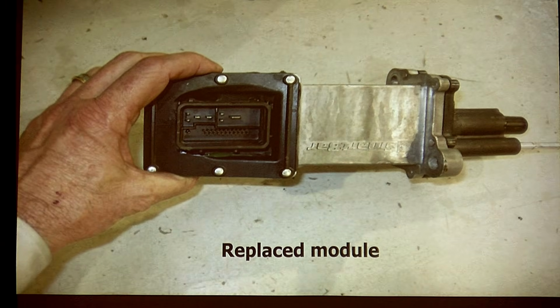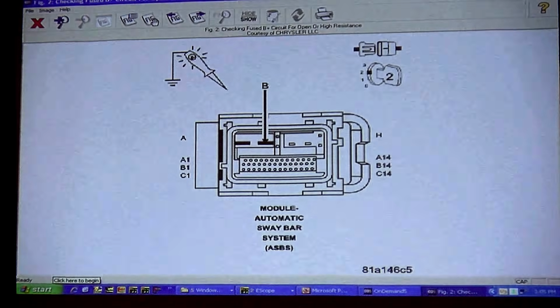Now I can do a count and a pin count so I can try to figure out which wires go in and what's what on it, right? Because the wiring diagram does not match the car. And we all have this, right? So you can't say, oh, how do I fix the car? You've got to figure out how you're going to figure out what the wiring is.